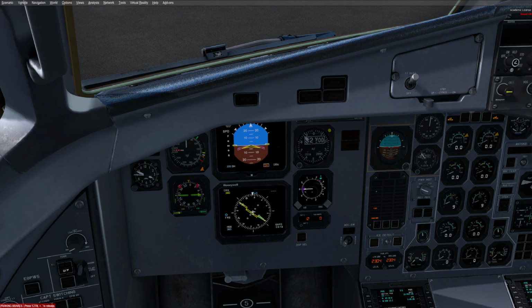You do not use the maximum continuous thrust unless you are in dire straits and a dangerous circumstance. Takeoff is used for taxiing, the takeoff itself, and on approach, landing, and taxiing to parking. Climb is used, of course, during the climb phase, and only when you reach your cruising altitude do you put it on cruise. And the preferred altitude in this aircraft is probably 18,000 feet. At that altitude, it gets the best true airspeed, and that seems to be the altitude that pilots like the most.